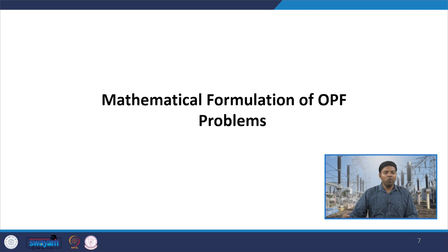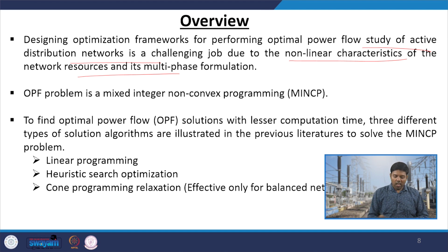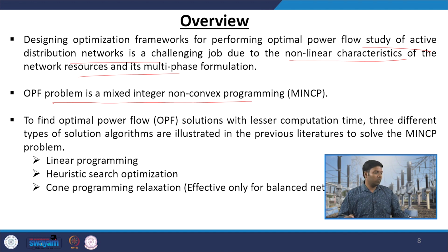So, now we will move forward with the mathematical formulation of the OPF problem. Designing optimization frameworks for performing optimal power flow study of active distribution networks is a challenging job. Why? We discussed that because of the nonlinear characteristics of the multi-phase formulation, right. Then that is why your OPF is mostly a mixed integer non-convex programming. Non-convex, that is clear. Why is that mixed integer? Because we have tap changing, that is an integer.